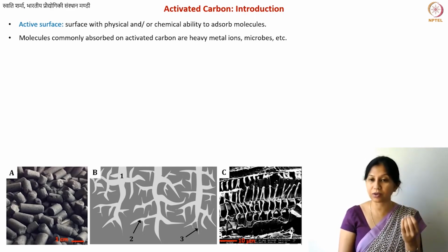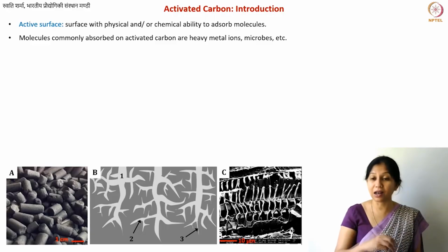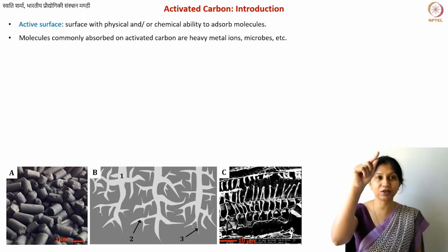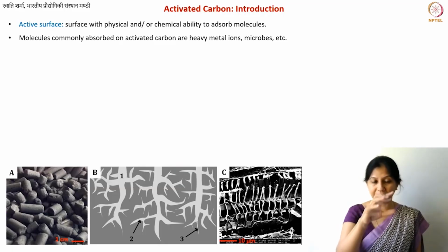And even very small molecules can get inside, they can get absorbed. Now the difference between activated carbons and anything formed by coking, for example glass-like carbon, there you have nanoscale pores, but they are closed pores. They are these fullerene-like structures, so nothing can go inside them. At least a lot of pores are closed pores, but here in this case you have open pores, pores that are percolated, pores that are connected to each other. So there is a sort of path the adsorbate molecule can take and can go deep inside.